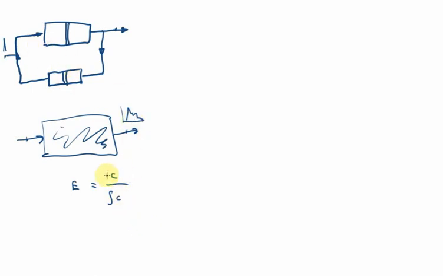So any signal that appears out here is going to be proportional to C, right? That's going to work out to some constant. So the exit age distribution is proportional simply to the concentration appearing at the exit. So let's see what kind of concentration we get here. So we assume that we are creating this pulse at time 0. So let's sketch out what we would get. So E as a function of, instead of time, I'm going to use age. So let's label the space-time in this plug flow part as tau P1, and this would be tau P2.